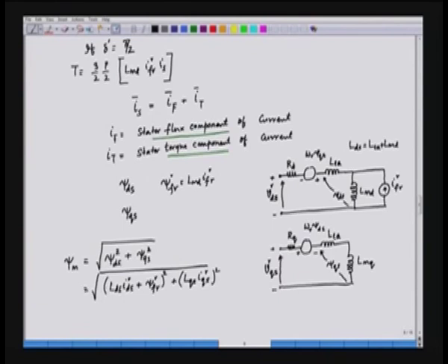has got the D component and the Q component. So, we can also call this the total stator flux linkage. And if we want to know what is psi m, we have to have the idea of Ids, the idea of Iqs, also the magnet strength, that is psi FR. Now, from this we can calculate what is psi m, and actually psi m is constant up to the base